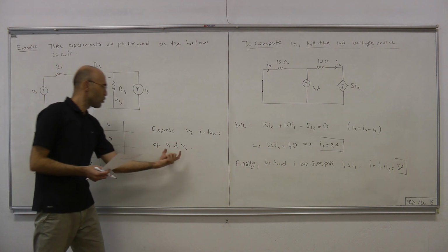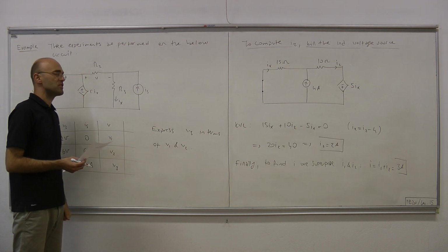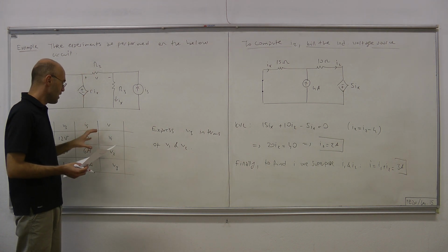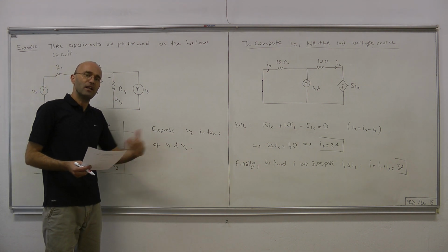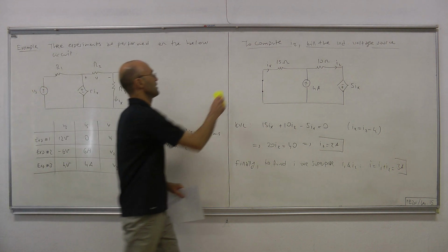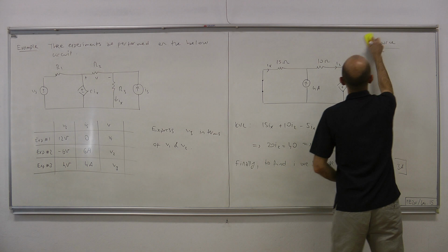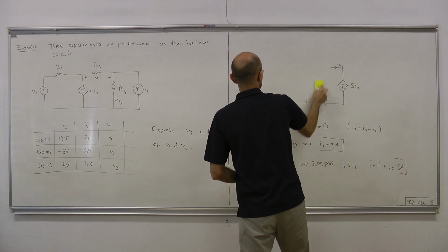It turns out that to compute that, you don't even have to know what R1, R2, or this lowercase r are. You don't have to solve the circuit. All the information that you need is in this table, plus, of course, the knowledge that the circuit is LTI resistive. Okay, so let's proceed to figure out V3, assuming that V1 and V2 are known.